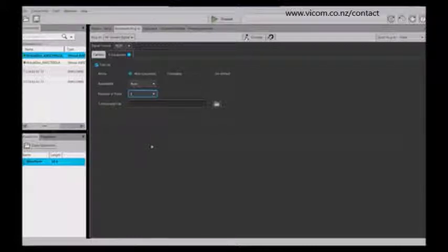You can just send the waveform from the AWG, but knowing that that component is basically built into the waveform. And this is another very useful tool for AWGs in the sense that you can build all of these characteristics right into the waveform, especially with the capability of 10 bits of DAC resolution on our AWGs. Gives you lots of flexibility as far as what you can do with these particular added characteristics that you want to build into the waveform.